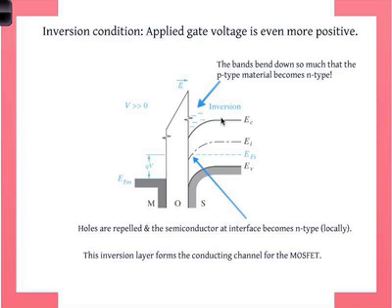Yes? So the p-type material sort of phases into N-type? Yes, exactly. So if I'm understanding correctly, then the resistivity would kind of increase as you move away from the... That's a good point. But think about which way the current is flowing. In this situation, the current is flowing out of the plane of the screen. It's not going through the substrate. Why? Because you have an oxide, an insulator. The current cannot flow left to right or right to left. But the resistivity of that flow...